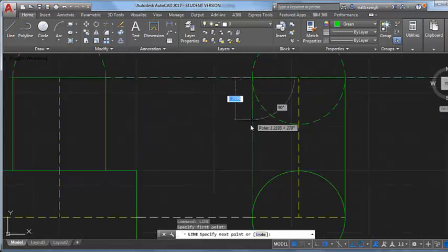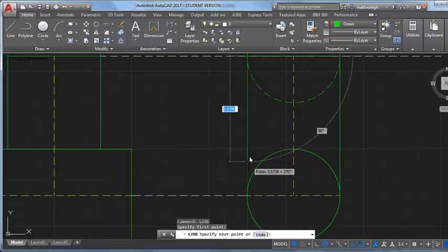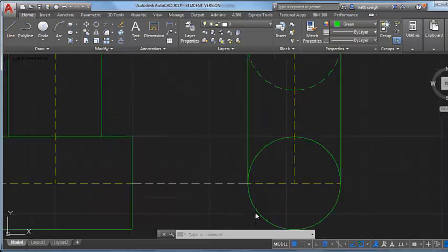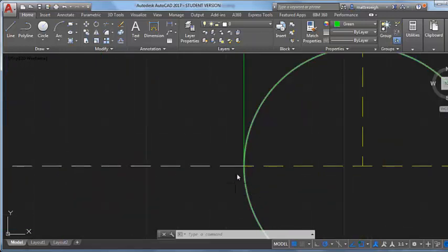Unless I'm dealing with big pipe with thick wall thicknesses, then the termination points are more related to the ID, and you get some of that stuff I was showing you at the beginning of this video, where we round those off and don't take those to such a sharp point. We're actually more aware of what's going on with our ID. Because if I zoom in here, with large diameter pipe, say 12-inch or 18-inch pipe, as it comes in to the center point here and then turns away from it, there's actually quite a distance. It's pretty straight here, and so I don't want to have to cut all that out.